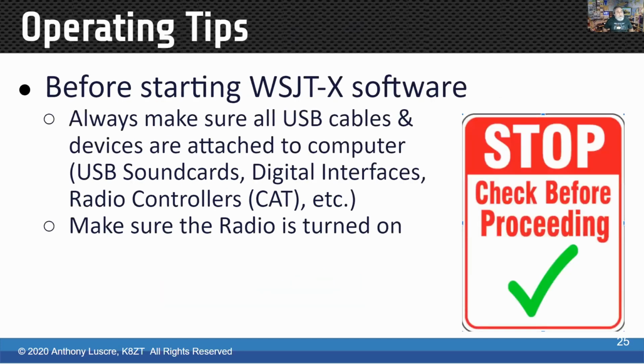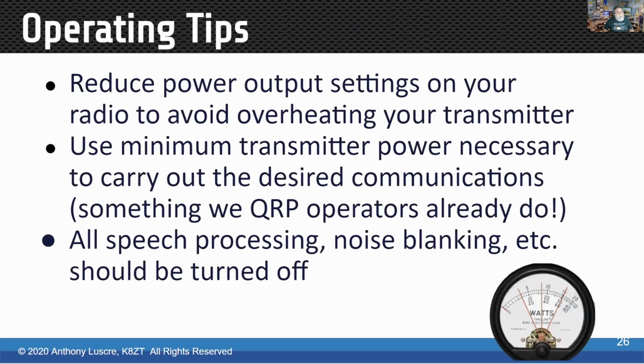Just a couple quick operating tips. Before you start the WSJT-X software, make sure you always have all your cables connected and your radio turned on before you start it up, or the software will look around and probably find the wrong interfaces. Most radios cannot be run at full power, since this is a continuous duty mode. Whatever you'd be comfortable running your radio with for RTTY or FM is typically the type of power you should be using.